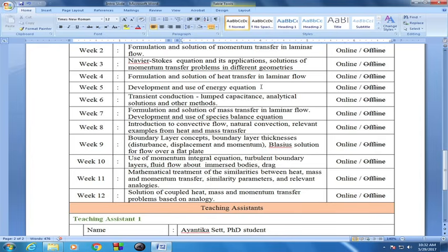and this friction will give rise to some heat generation. So, heat generation by external sources, heat generation by fluids flowing past each other, the work done by the system or the work done on the system, all these will constitute different terms of the energy equation. So, we will derive, discuss, simplify and solve energy equations with relevant boundary conditions. Again, the goal is to obtain the temperature field, the temperature at every point in the flow field, which can then be used to derive quantities of engineering importance, such as the convective heat transfer coefficient. We will see that subsequently.